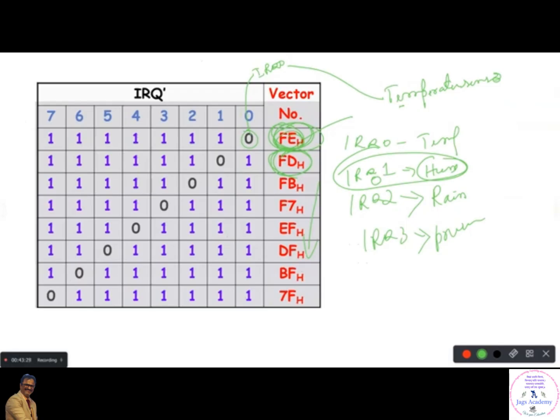Multiple people want to communicate data, right? And I have told you that this particular arrangement can serve only one interrupt at a time, because it does not have that priority encoder. Suppose, as I told you, that both the temperature and humidity sensors want to send data. Those two are separate sensors, so they go through separate requests. Of course, the microprocessor will be interrupted, but the data which goes is something different from what is specified here. So that is a drawback in this particular circuit.